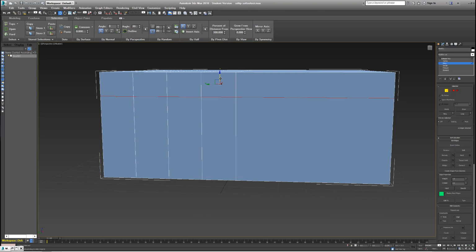I'm actually going to use only the Z to drag that down a bit, because I'm trying to create some windows and doors here. Drag that down, the Z axis, hit Q to get out of that. And let's say I need another bottom edge for this window, so I'm going to hit the chamfer settings, same as we did last time. I see that 3 is a bit too much. I'm just going to drag that down to 2. I can increase the distance between my chamfered edge by scrolling up and down.